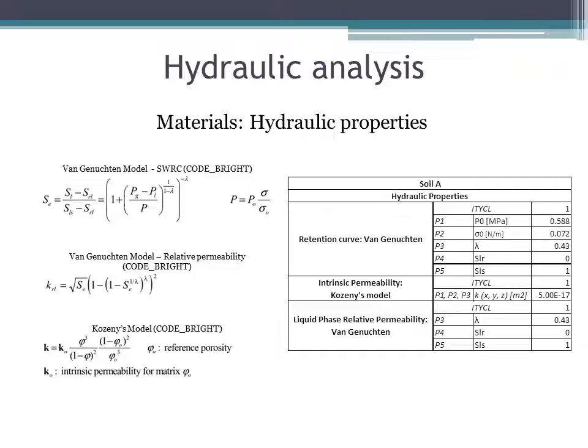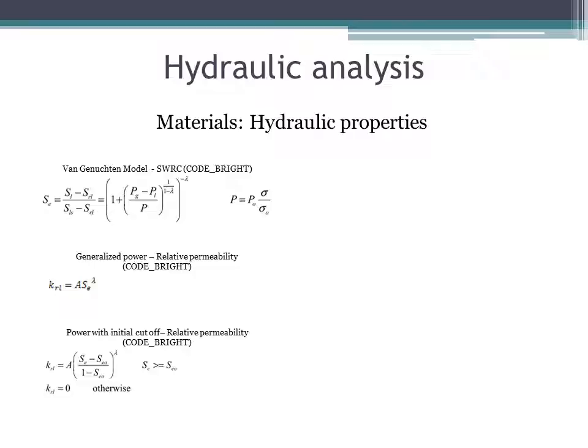The program requires also a function for the intrinsic permeability that changes with porosity, even if porosity is constant in the model because no displacement is calculated. Because the water and the permeable columns have also been modeled as materials, the hydraulic properties for them have to be assigned.